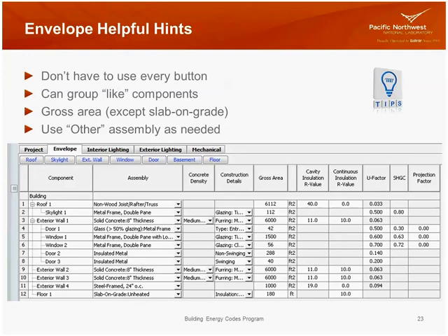Then there's another column there that shows square foot, but the last row on here shows a slab on grade, and then it's in feet. Slab on grade is the only entry where you'll enter that component in linear feet, that exposed edge.